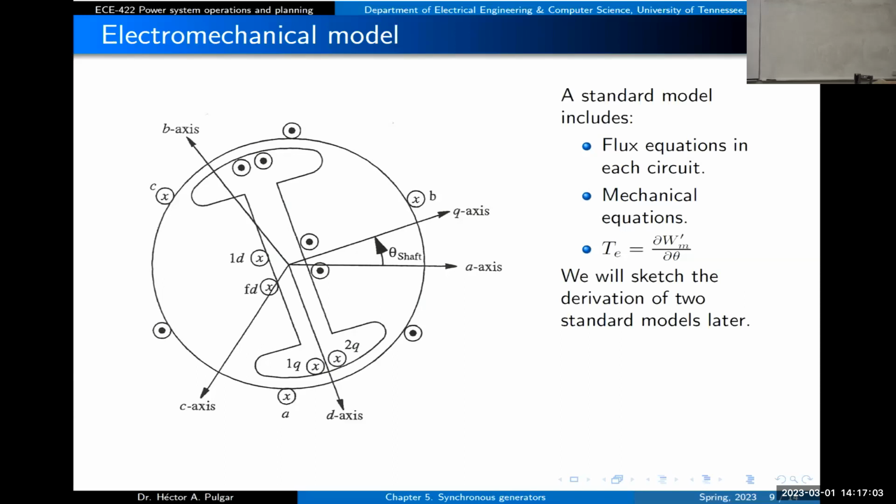So these are synchronous generators. The rotation of these should be constant, the synchronous speed, nominal speed. So in a steady state, what we expect is that the net torque applied to the shaft will be 0. But because the system can have disturbances, this net torque sometimes will not be 0, right? And that will create oscillation or disturbances. And when that happens, these dampers should help this machine find again that point in which the net torque is 0, and the machine again rotates at synchronous speed.